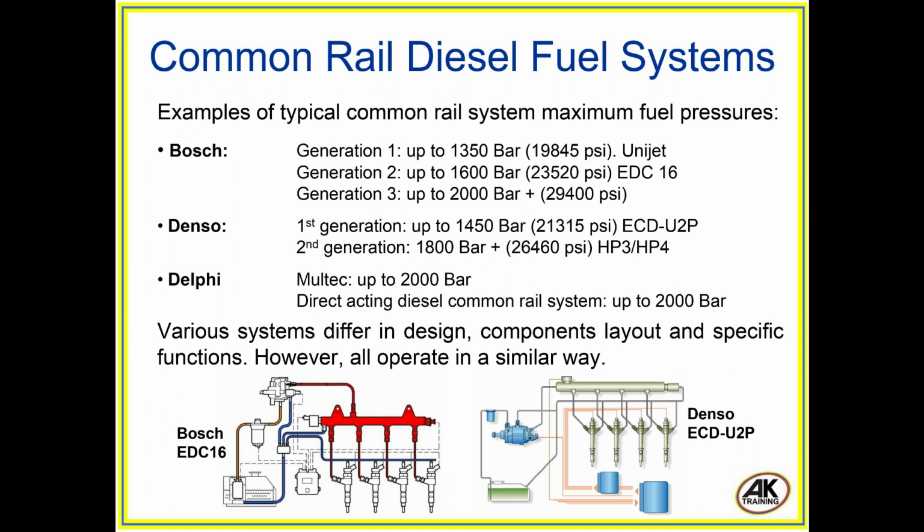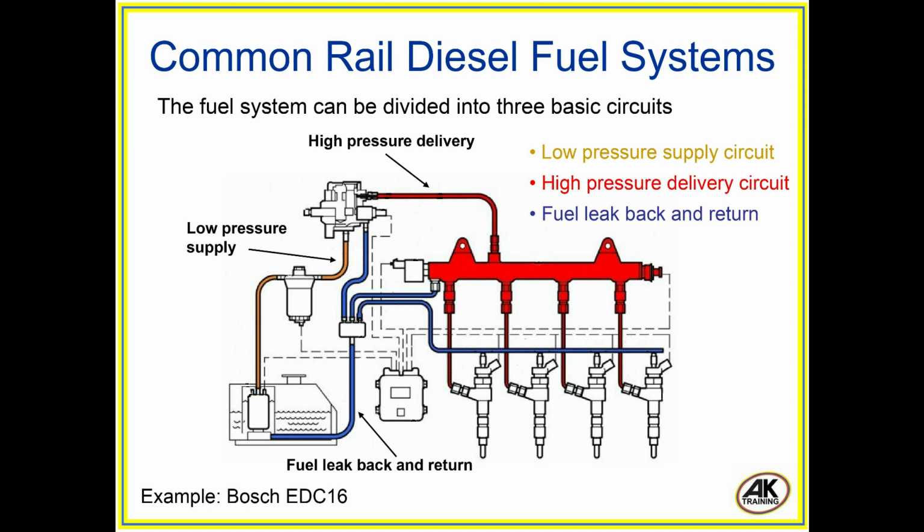Various systems differ in design, components layout, and specific functions. However, all operate in a similar way. The fuel system can be divided into three basic circuits. Low pressure supply. High pressure delivery circuit. Fuel leak back and return.